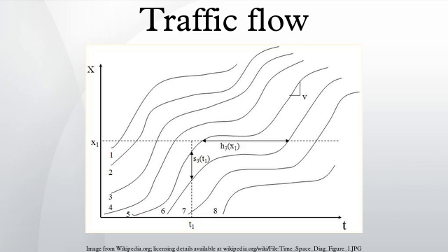3. The understanding of highway capacity as a particular value fails because this assumption about the nature of highway capacity contradicts the empirical evidence that traffic breakdown can be induced at a highway bottleneck. 4. Dynamic traffic assignment and any kind of traffic optimization and control based on Wardrop's SO or UE principles fail because of possible random transitions between the free flow and synchronized flow at highway bottlenecks. Due to such random transitions, the minimization of travel cost in a traffic network is not possible.